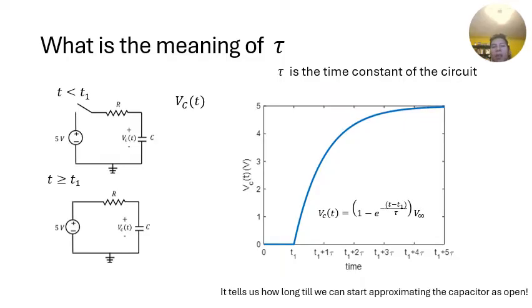Okay, in particular, what we're going to do when we try to figure out what these frequencies are is try to find the R Thevenin looking into each of the capacitor terminals, to determine what the equivalent resistance is that each capacitor sees.